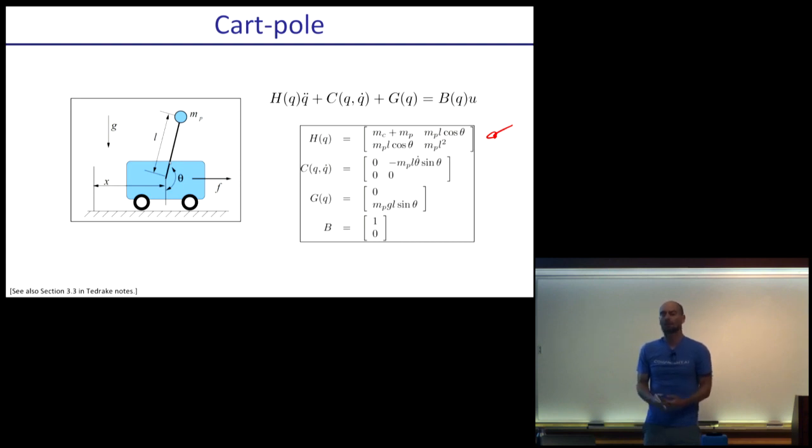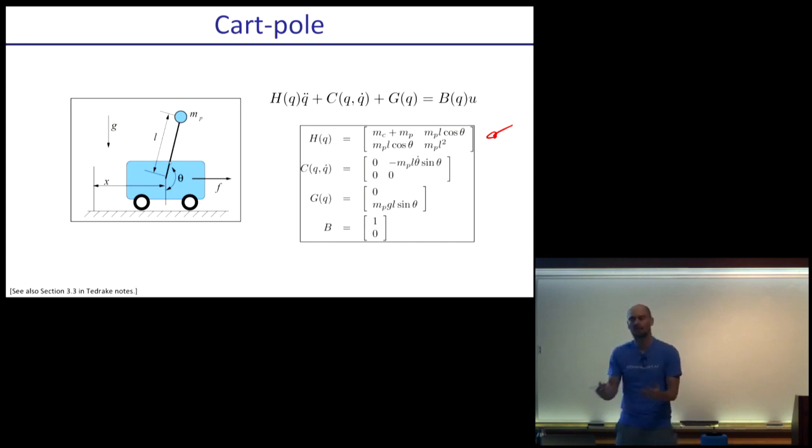But if we want to balance cart pole, we can say, okay, let's find the linear approximation around the equilibrium point, which is the one with the pole up and x at 0, and then run LQR on the linear proxy for the system, find the sequence of linear feedback controllers, or for infinite horizon, find the infinite horizon feedback controller, and use that to control the system.